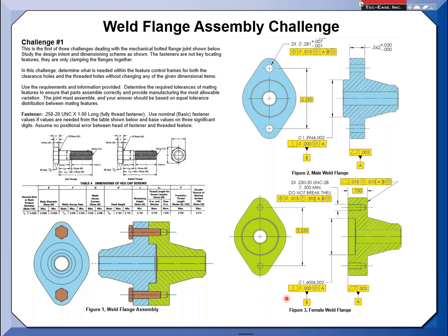Now, have companies put position in here? Because they say, well, with position, I control orientation. I've seen that, but I can speak for aerospace companies. We have some very rigorous people reviewing the technical drawings. They would redline that position out and mark it up as an orientation control only. So depending upon your company, the standard does not show anything along those lines when it's just an orientation. I don't know if that helps.